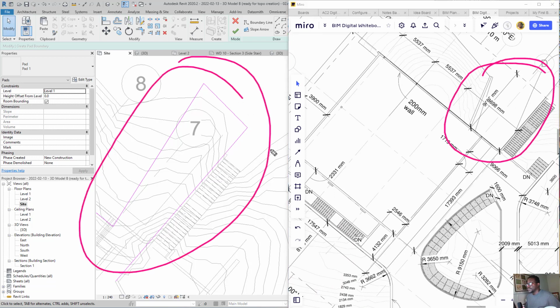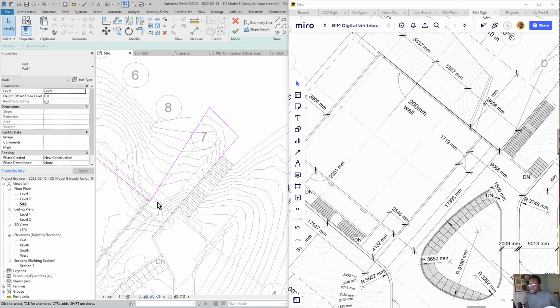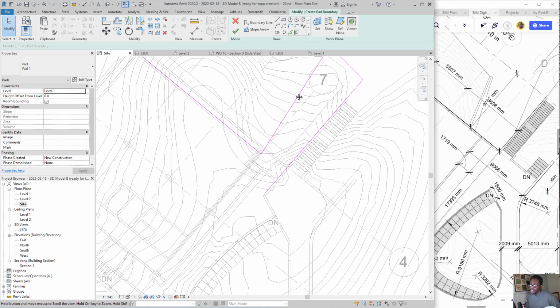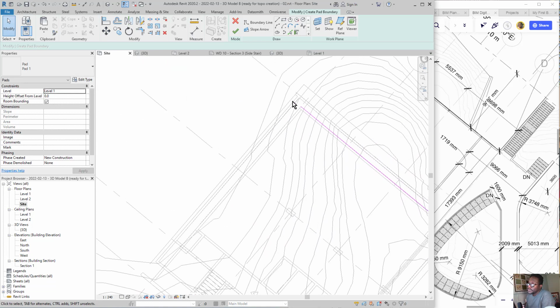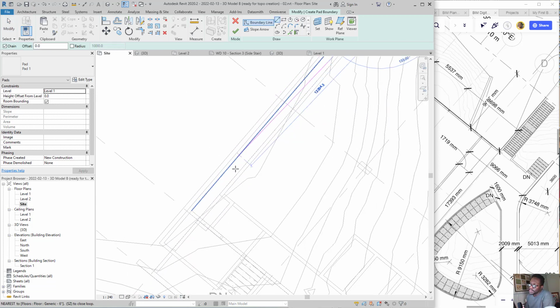Now we haven't drawn in this wall as yet, right? This is more of a custom wall, but we can always edit this building pad. So we're going to use the whole Revit revise it method. So we're just going to put in a sketch of it, and then we will revise it as we detail out this model, right? All right, now I'm going to continue to excavate all along here.